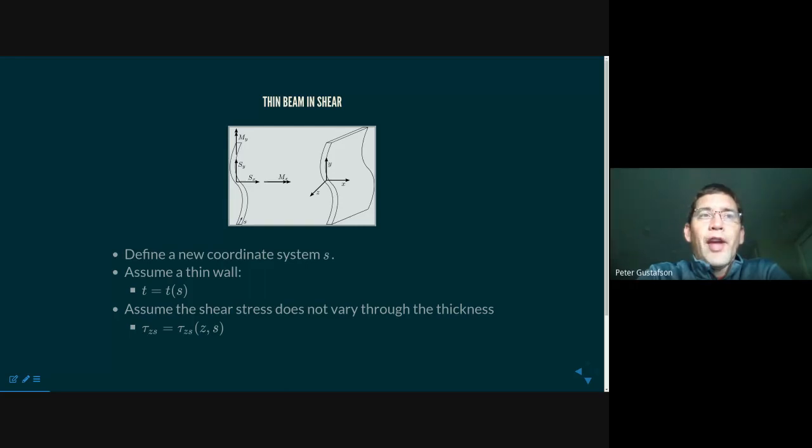We also said that when it deforms, assuming that the beam is long, we observed that plane sections remain plane and they remain perpendicular to the neutral axis. Just to remind you, we watched that YouTube video because if we were in the real lecture hall, I would have brought my own foam beam and we would have bent it and thought through all of those problems. In this lecture, of course, we had to do it with a YouTube video, but I think functionally it ended up being able to communicate that to you.